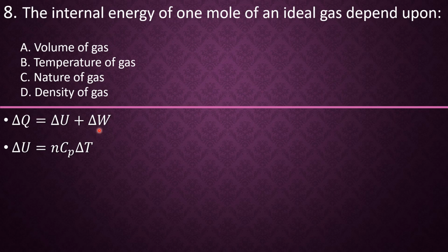And so our du, which is basically n Cp delta T, well, you're heating a gas, and so you can heat the gas at infinite numbers of heat capacities. But the two most common heat capacities for gases are basically heat capacity at constant pressure and heat capacity at constant volume. So you can actually use the heat capacity for constant volume if the gas is heated at constant volume, which in that case would make the thermodynamic process an isochoric or isovolumetric process.